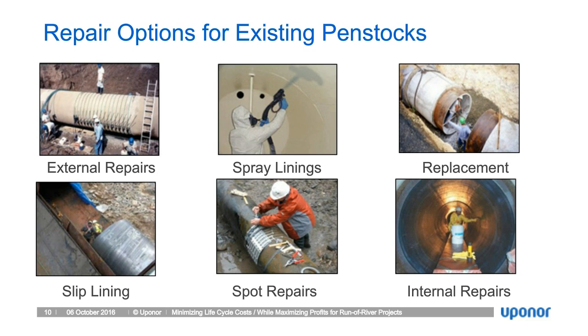The con with liners is that they are liners and they do wear out. So if you're taking any sand or any abrasive material that's going to wear those down, you're going to lose that advantage and re-expose the steel or other materials.